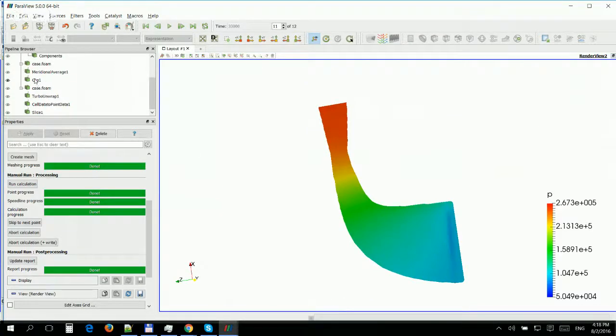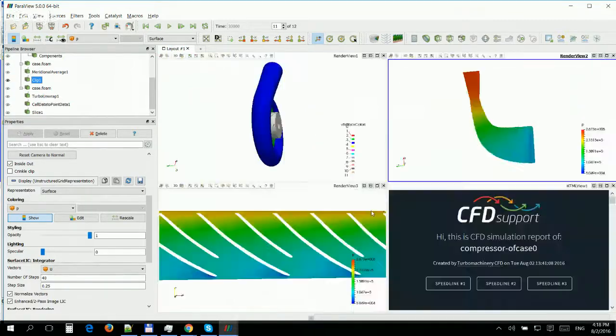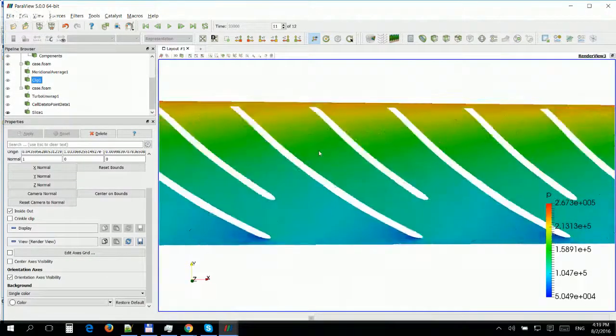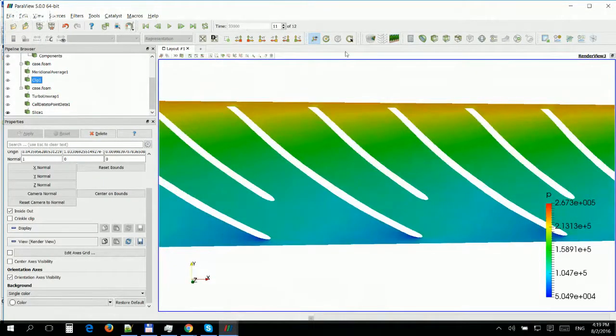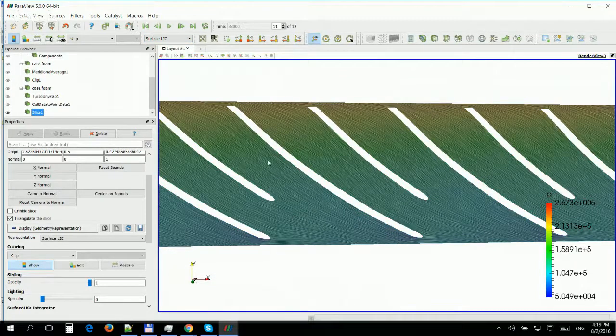And for example, blade to blade, which is again quite important at any level between hub and shroud. You can specify how you want to see the flow. How is your flow developing? You can see stream traces via surface LIC filter. You can see separations.